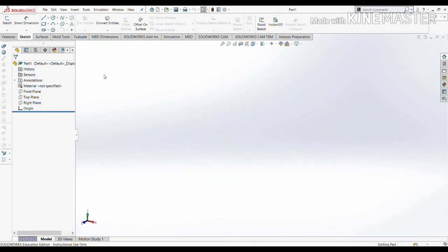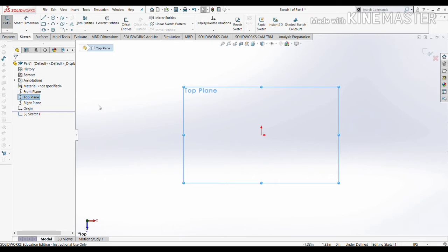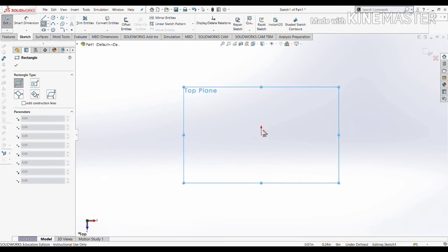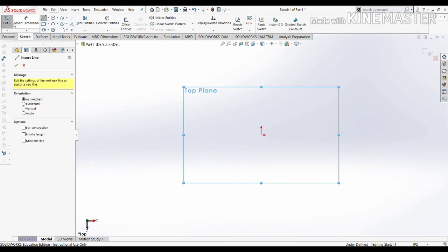So if I wanted to say, let's start a sketch on the top plane, what I can do is I'll click the top plane here, and I can click sketch. So now I'm in a sketch. That's the easiest part right there. We're almost halfway there to making our first thing. So what you'll see up here is it opens all of these options at the top. All of these were grayed out before, and now they're able for me to click.